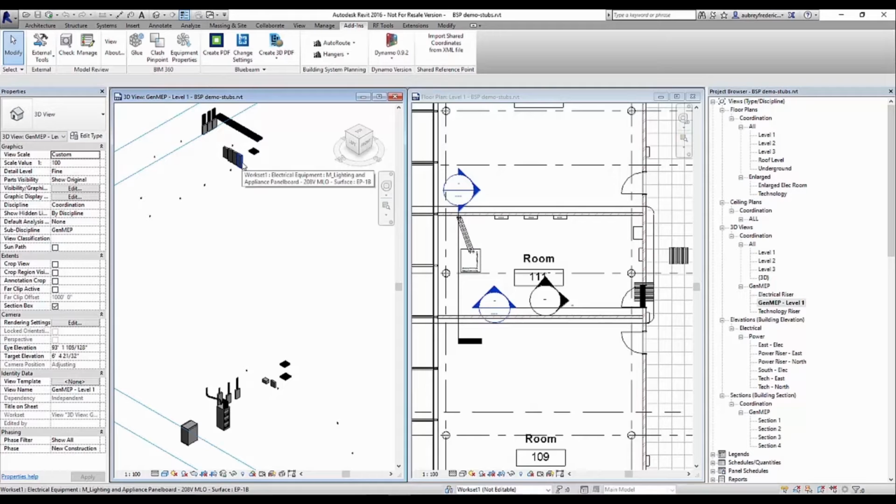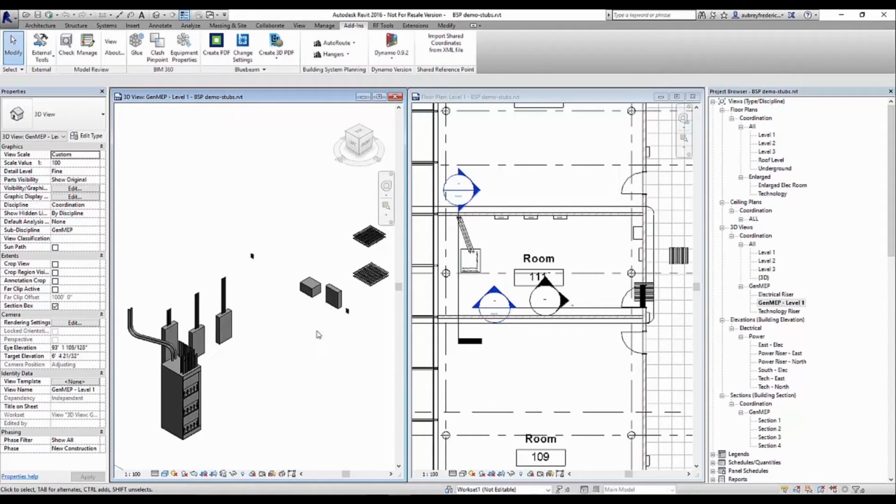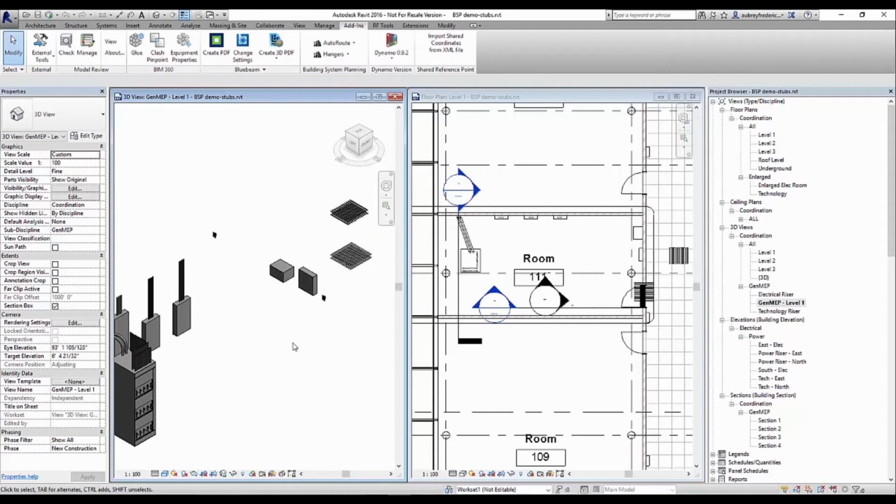We normally lay out these little groups of stubs and use the fillet command, whether we're in AutoCAD MEP, or in Revit, the trim command. So essentially, GenMEP has our workflow in mind. It's pretty nice to see the ways that you could use these stubs that we would normally place in the model anyway.